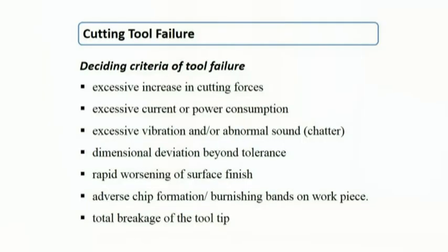One is that if the cutting forces are increasing suddenly during the cutting, then it may be the reason of tool failure. Because by failure or by wearing action, there may be the chances that the sharp edges of your cutting tool become blunt, and due to those blunt edges, there may be the generation of larger cutting forces to machine the component.